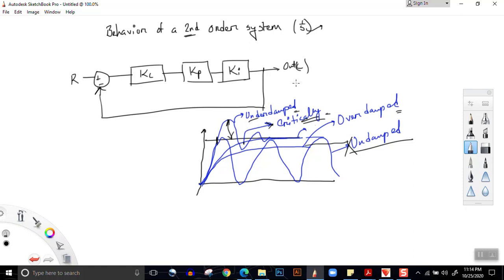So technically, it may seem like the critically damped system is our best for any type of operation, because it is a balance between the speed of the underdamped system and the high stability of the overdamped system. But that might not be the case. It actually depends very much on the kind of operation we are using it for.